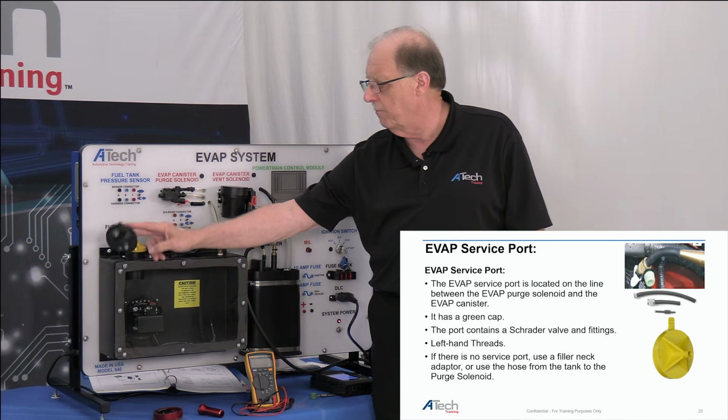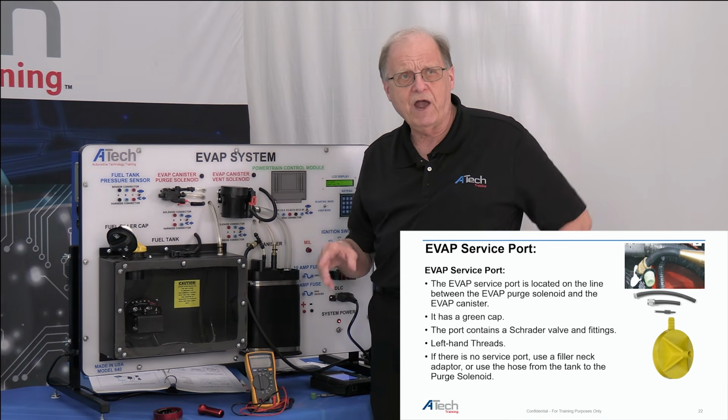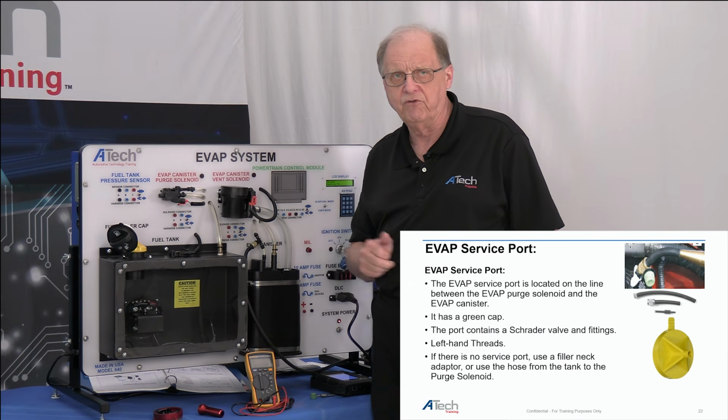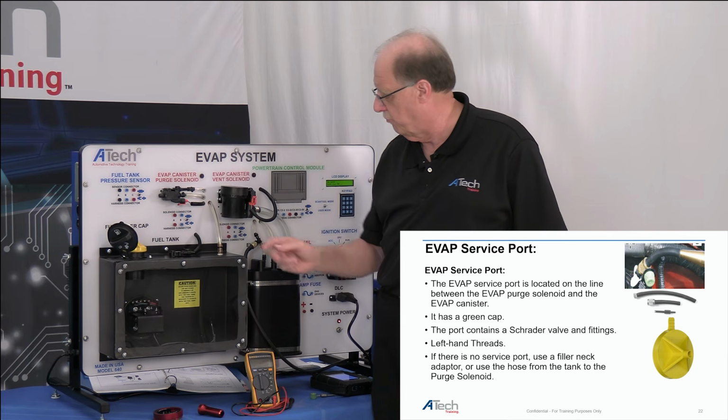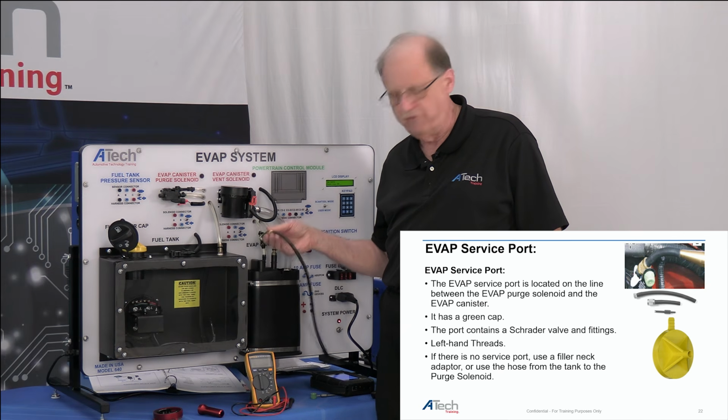The other thing I wanted to make sure everybody knows, that's a yellow one for most of the cars, but if you got a BMW or Mini, there might be a black one. If you look at the top right-hand side on the slide there, you see where that green service port is, and you see the tools for doing the process. There's a little tool that is hooked on right here that will allow you to hook up my hose into the system.